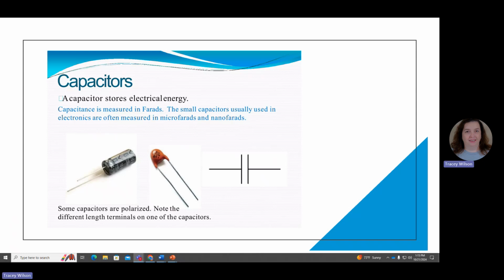Now, this is not as big a deal to you guys at this point, but back in the day when we had the CRT monitors, the big heavy monitors, you might remember them from your childhood. They actually would have some capacitors in them that would hold charges for very long periods of time, even after being unplugged. And it was enough that it could do you some physical harm. Maybe you have like a heart condition or something, it could even potentially kill you if you didn't discharge the electricity in the correct way. So don't play with old TVs and old monitors. It's a very slim possibility this will ever happen. But just be aware you can get shocked.